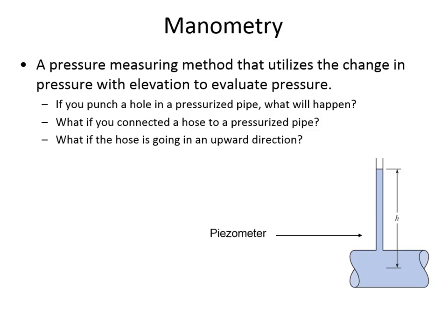So if the pressure was low, 250, then the delta H would be around 25.5 meters of head. And they call this head when the water rises a certain distance above the pipe. Pressure and head are related.